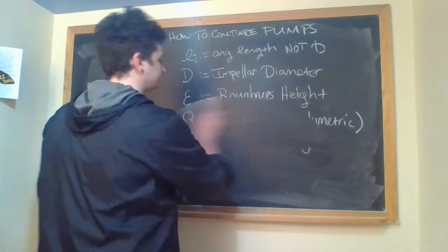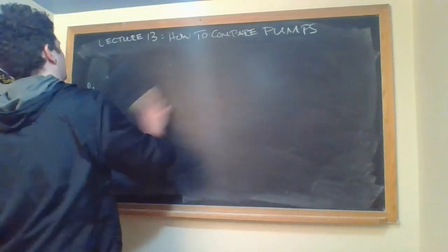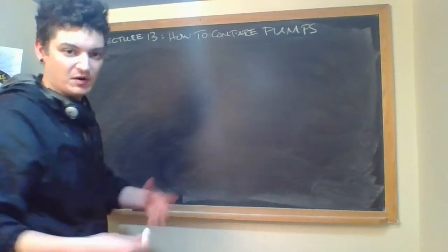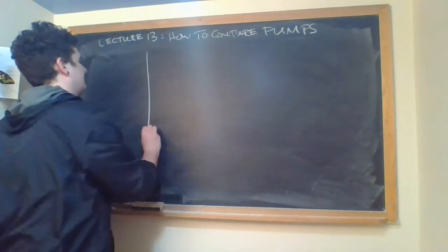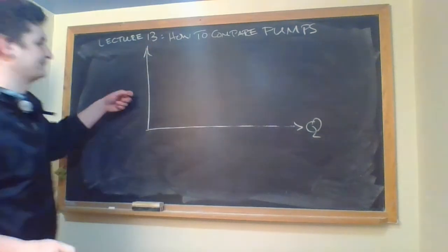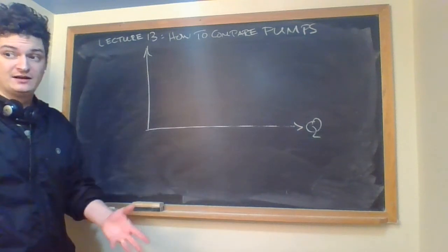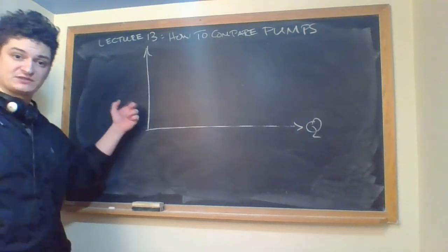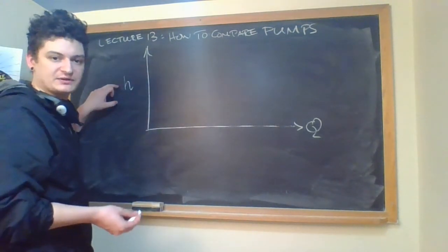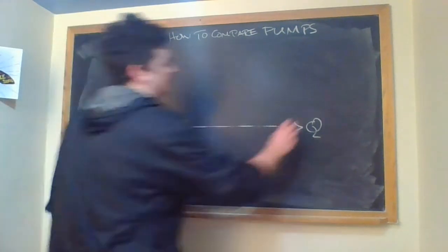So now let's shift into what do you want to predict? What are you trying to characterize with your pumps? Motivationally, let's just go back to these system curves that we have. What was this axis? If you're trying to figure out what you want to predict based on non-dimensionalization, which is where all this is headed, go to graphs that you look at and see what's my y-axis. So the head of the pump, or a delta P of the pump. Head rise for pumps is something you want to characterize.